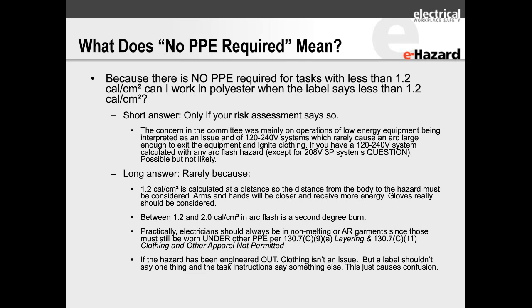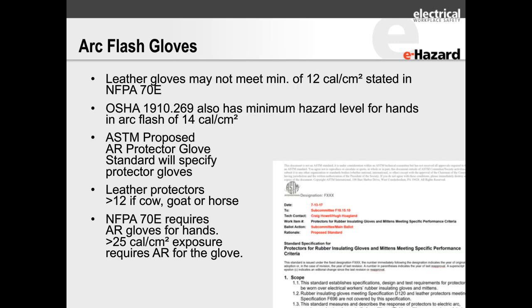Arc flash gloves. There is an arc flash test method for gloves. It doesn't require rubber gloves or leather gloves to be tested, and most companies have tested them. You can get that information from your manufacturer. Rubber gloves will ignite, but honestly, it's rarely ever happened. I mean, one or two that I know in my whole career, and I've been involved in 160, 170 accident investigations as a consultant on one part or another, and I've done about 25 or 30 in-depth investigations in the course of my career. So I've seen a lot of this, and I've talked to a lot of people in this situation.